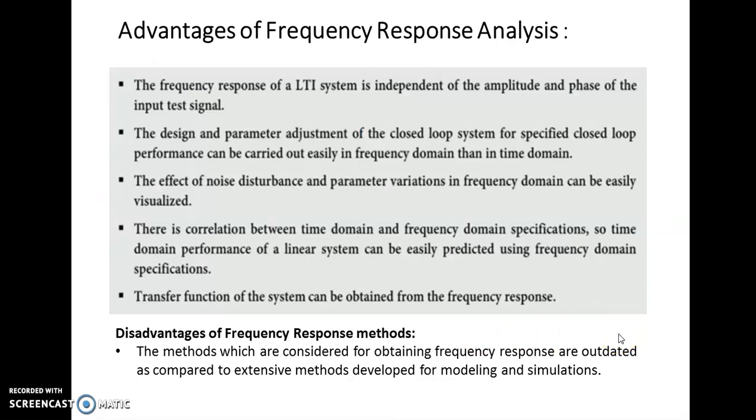Frequency response analysis has advantages and also disadvantages. The frequency response of a linear time invariant system is independent of the amplitude and phase of the input test signals. The design and parameter adjustment of the closed loop system for a specified closed loop performance can be carried out easily in the frequency domain compared to the time domain.